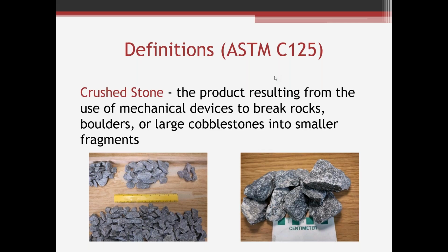That's probably the most commonly used coarse aggregate, at least in our area, although you do see some of the natural gravels. But the crushed stone is pretty readily identifiable just by looking at it, based on angularity, and a lot of times the color, all very similar sizes, similar textures, things like that.